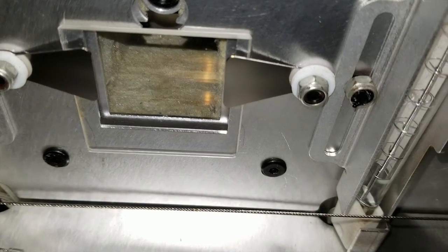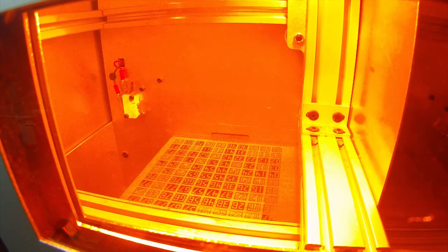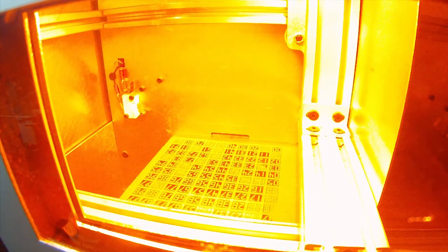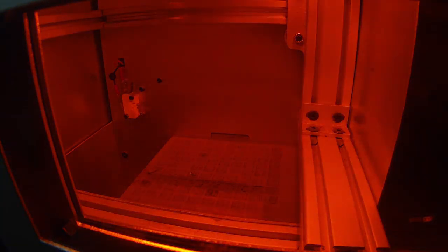Another thing that isn't in this particular video, but you can kind of see it, is that on numbers 8 and 9, I had a bit of a shadow. I talked about it in the other video: the laser couldn't actually get to the powder because something was blocking it, either in my glass that's on the underside of the ceiling, or maybe something to do with my insulation. My insulation isn't properly aligned with the metal grid. So if you look down at the bottom right, the front right, you'll see that numbers 8 and 9 don't actually center into a square. They kind of look like a trapezoid because the laser can't get to it. All right, so that one was at 173.7.